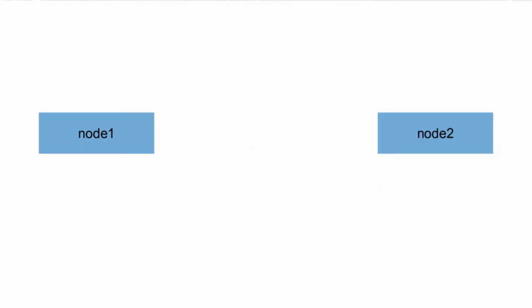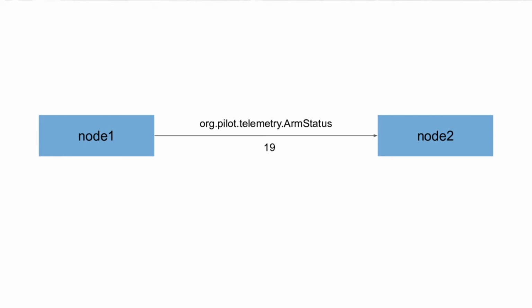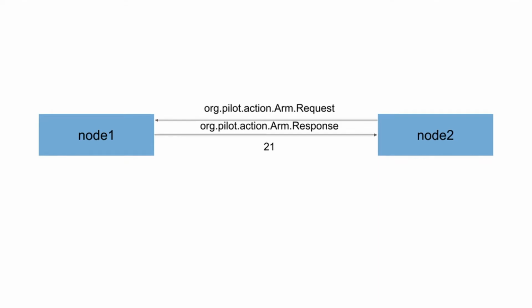Like ROS, UAVCAN facilitates publish-subscribe communication on subjects or topics between nodes. Instead of topic string names, however, UAVCAN subjects are identified by numerical subject identifiers. Similarly, UAVCAN nodes can also send requests, identified by numerical service identifiers, to other nodes and receive a response. Combined with UAVCAN v1's new ability to work across multiple transports, including UDP-IP, we decided to experiment with building a DDS for our ground control stack based on UAVCAN.